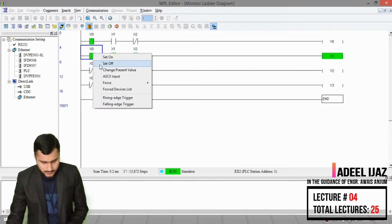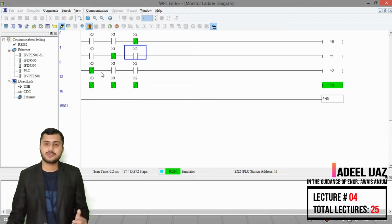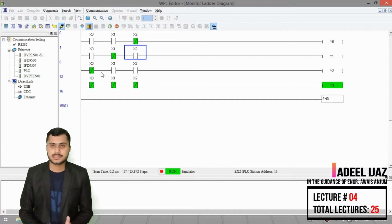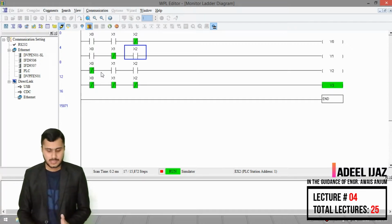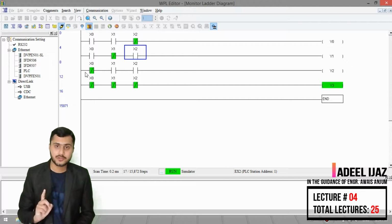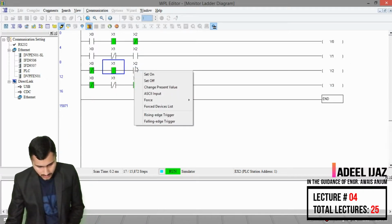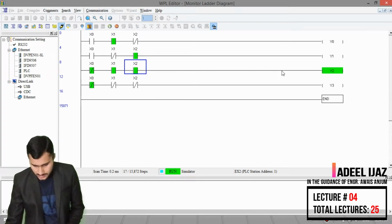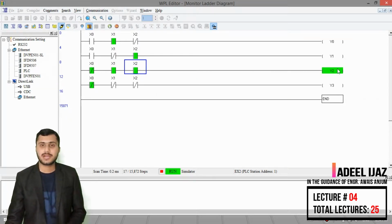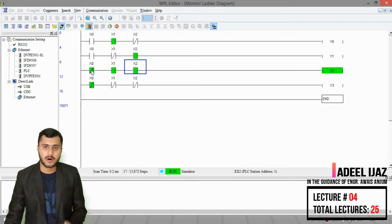Now I turn off the x0 and turn off the x2, and according to our third condition, if the last two switches are on, then our third output, which is y2, will get activated. But at the same time, x0 should be off. So if I turn on the x1 and turn on the x2, you can see that our third output, which is y2, is now activated. And at the same time, our first switch, which is x0, is off.